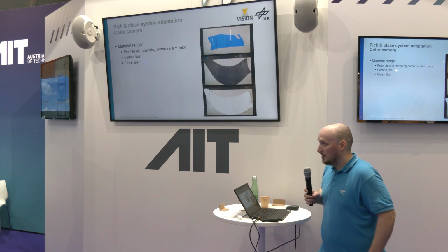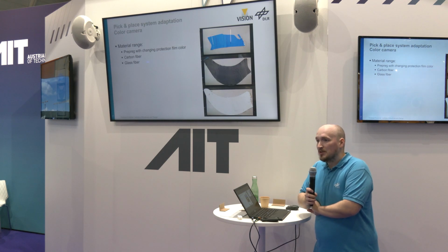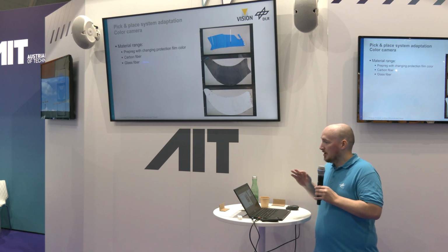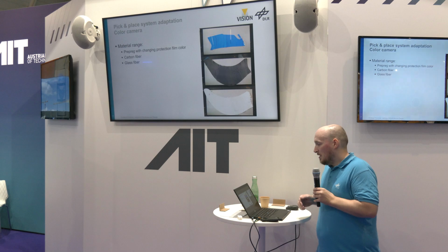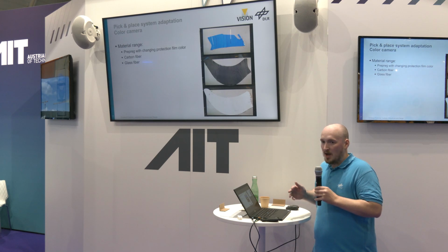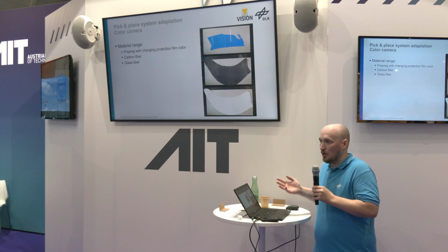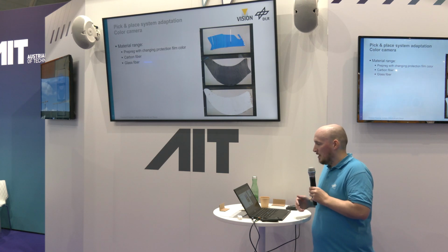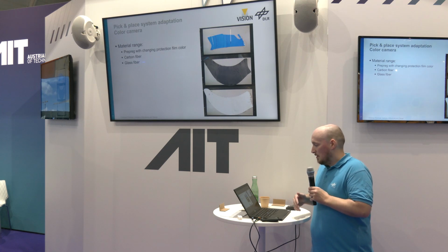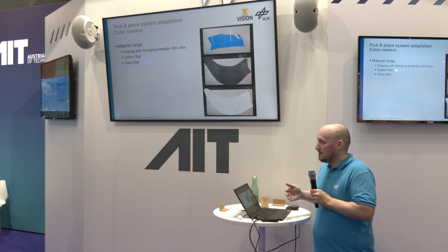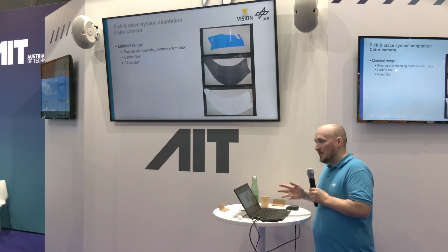But for the new system we needed to use a color camera. And here you can see why. The other use cases are using other materials like pre-preg, where resin is already in the fabric. They are delivered with protection films on top and beneath, and they have color changes with every batch, and you don't know which color it will be. For the propeller, we had carbon fibers and glass fibers. Glass fibers we never used before, but you can already see down there that the background is not quite different from the fabrics themselves.